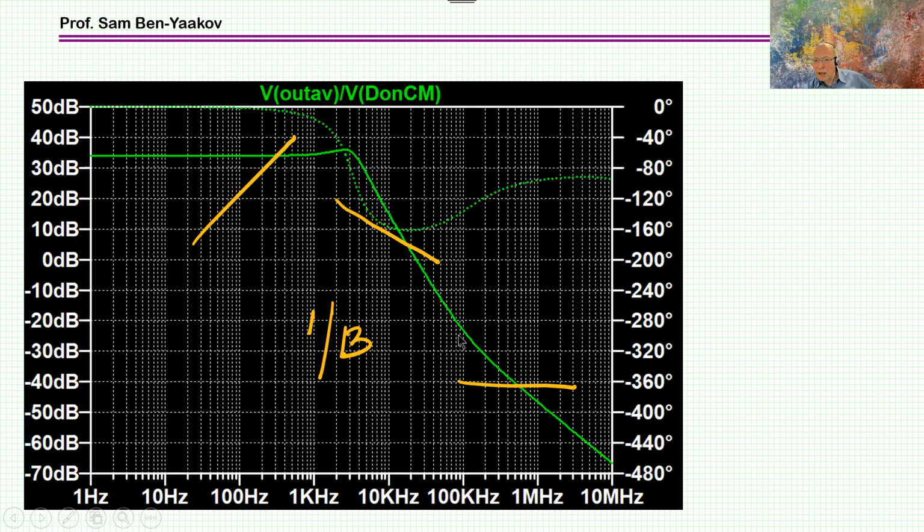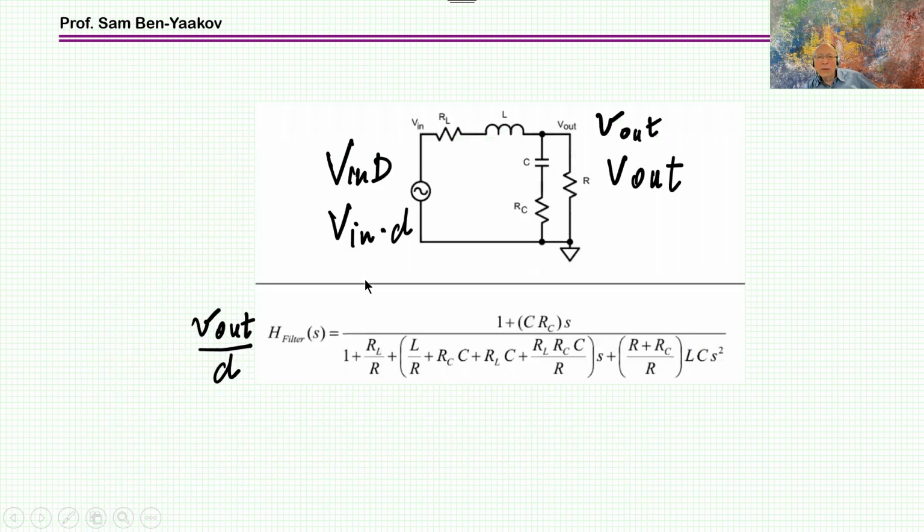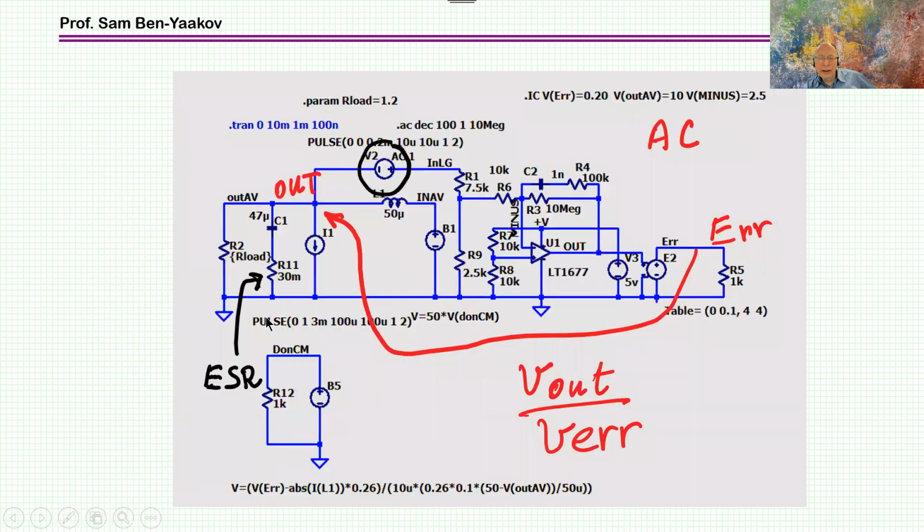So I'm showing the difficulty of closing the loop on a second order system. And this is why we want to add the feedback, the current feedback. And now I'm showing from the output of the error amplifier to the output, the whole thing, including this equation, because now I am including this equation in this path.